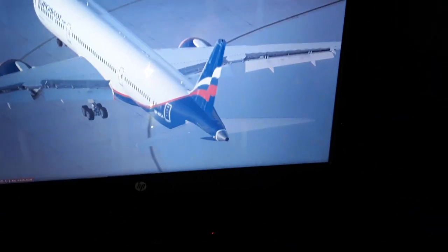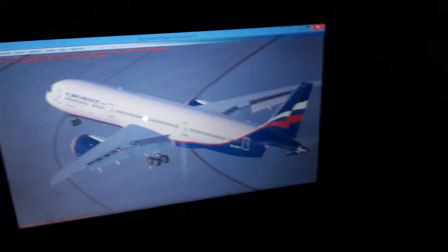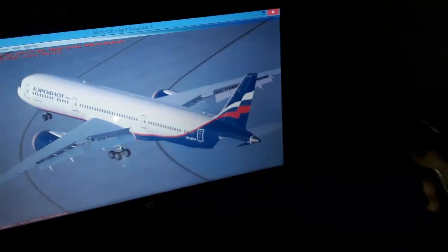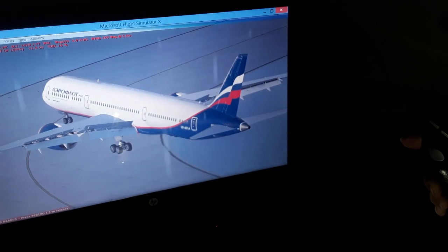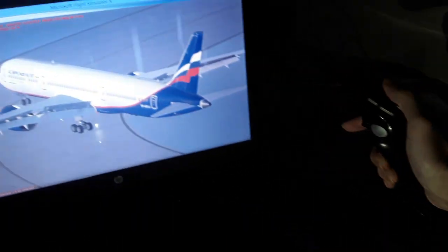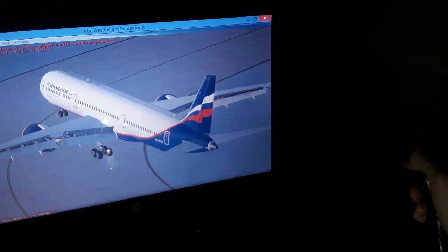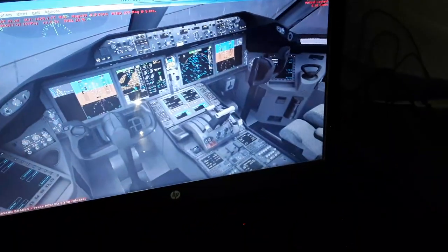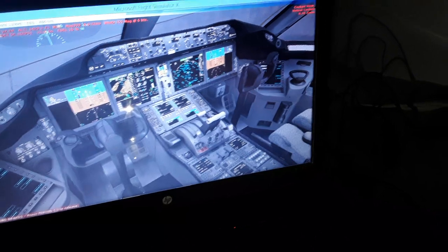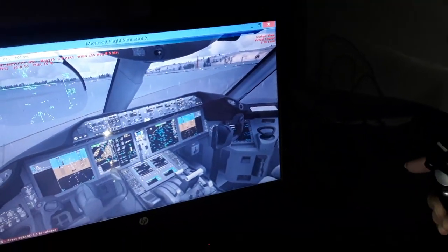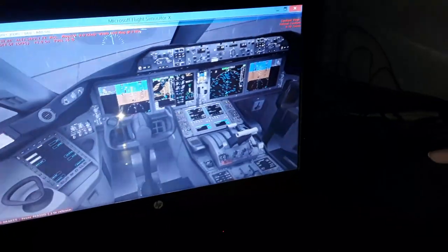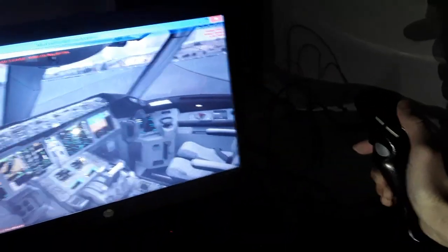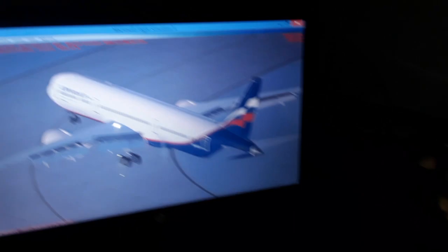So you can see the rudder, the yawing axis, also the nose wheel, as I explained right now, the forward nose wheel. You can deflect it alongside with the rudder pedals. So this is how we use the rudder pedals. Also, in flight you have only the rudder; on the ground you have both rudder and nose wheel for some airspeeds. So we have also another axis over here.